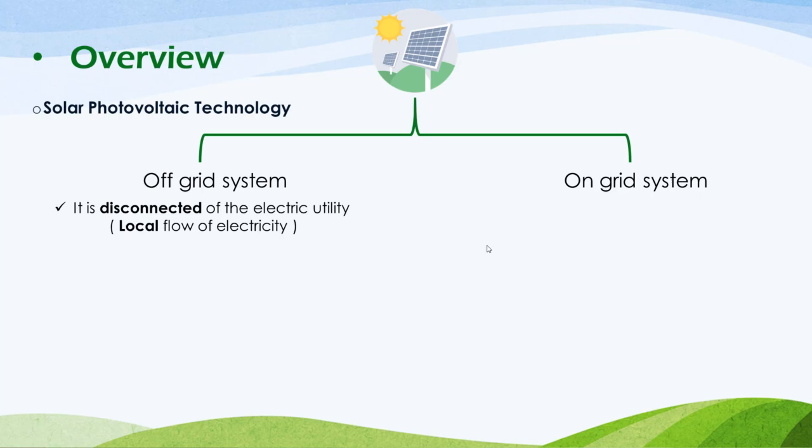The components of the off-grid solar system are the solar panels that receive the sunlight, then convert it to a direct electrical current, and this direct current, or DC current, goes through a charge controller. The job of the charge controller is to control the flow of the DC electrical power from the solar panel, and the power gets out of the charger to enter the batteries.